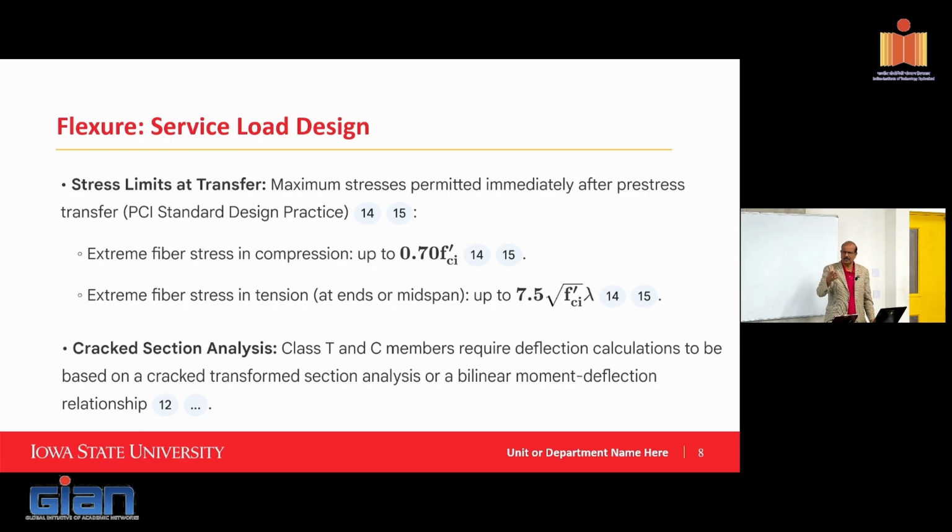Blanketing the strand, I don't know, Satya, what you guys use here, what they call blanketing the strand, where they debond it with sheathing around it. Actually, for the end region, sometimes we used to get top reinforcement coming at the end for taking the negative moment. We used to debond by using a plastic pipe filled with grease. Right. Okay. So these are the tricks that precasters have